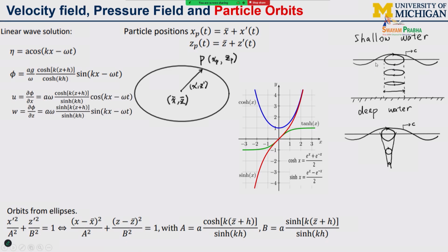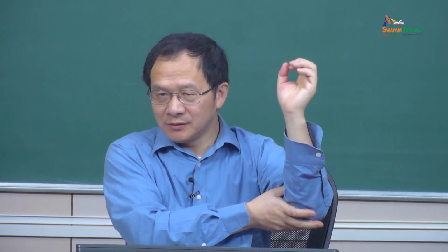However, in the shallow water it is different. In shallow water you still have the horizontal dimension. So look at this one. If you design some wave energy converter, right, for the shallow water to work, you probably want to make use of the horizontal motion. For example, you have a surge wave device, right? Take advantage of this surge motion, because the surge motion amplitude doesn't decrease, right?